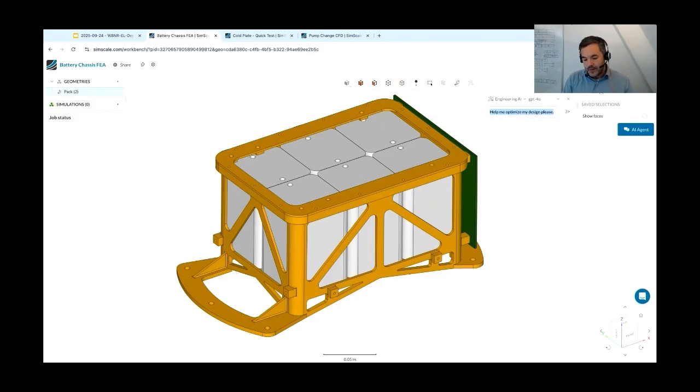Now this agent has been instructed how we typically run these kinds of harmonic response analyses, what our standard materials are for certain parts that it recognizes in the CAD model, etc. So what I can now do is ask: what is the harmonic response of this design to our standard load case, given our standard materials and CAD labels, fully automatic, please. Again, I haven't checked the detailed instructions of this agent, so we'll see what it does.